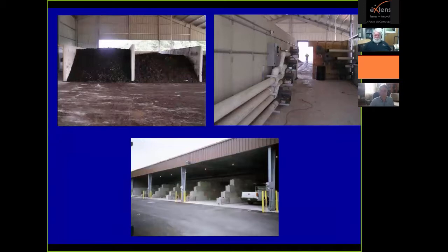These are the kinds of enclosures that we see used in compost aerated static pile. On the upper left, we see reinforced concrete, often used to create the walls. So each one of these bunkers is a fixed volume. I normally size them so they can be filled in 2 days, 3 at the most. The advantage of reinforced concrete, you see in the upper right, you can hang all your electrics and your piping and everything on the back wall behind the compost bunker.